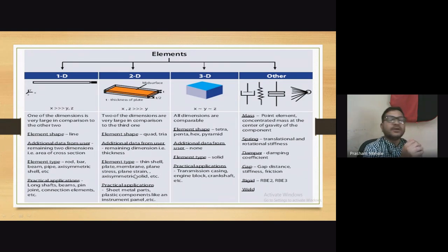Whenever you are not going to get accurate results, or otherwise the output results are deviating from actual, okay, actually the results are different, and suppose the analysis is giving a result with a very large deviation, having a large error in between. In that case, the first job that is done is change of shell. What is the meaning of that? Change of shell is change of element.